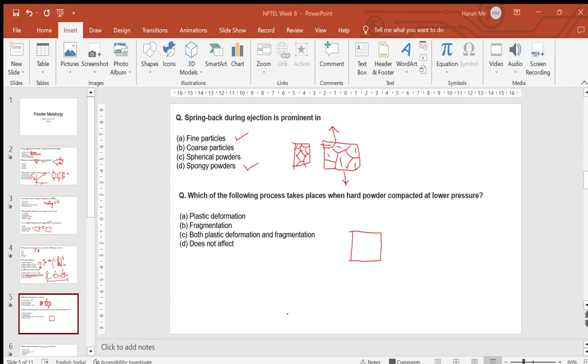So you have to see, copper has the highest green density. Then nickel. You are having copper as the first, because it has lower yield strength, so that's why its green strength will be highest. Copper, then nickel, then zirconium, then molybdenum, then tungsten. Because if yield strength is more, work hardening will develop during compaction, and so your green density will be lower.